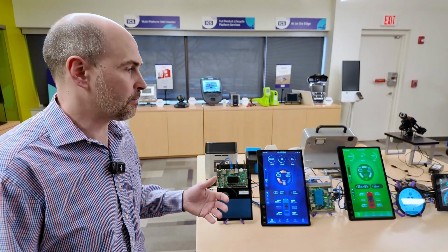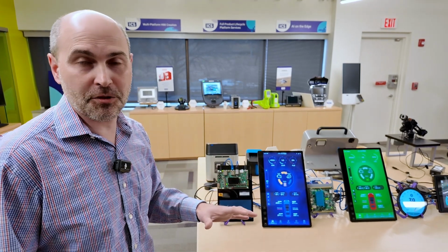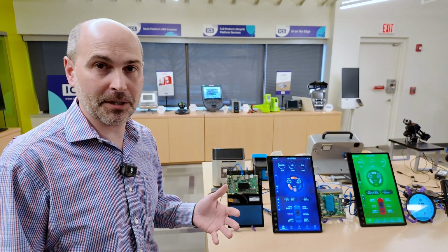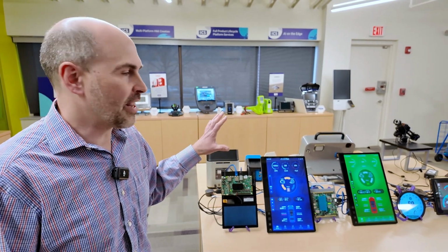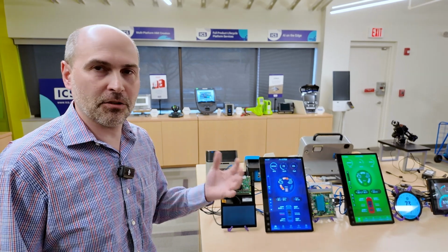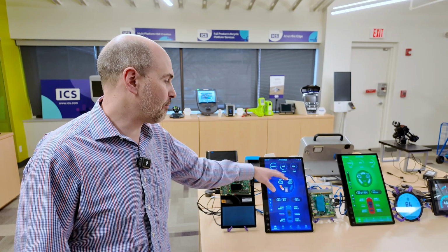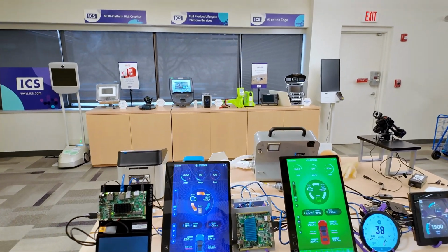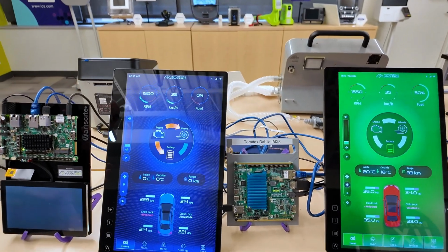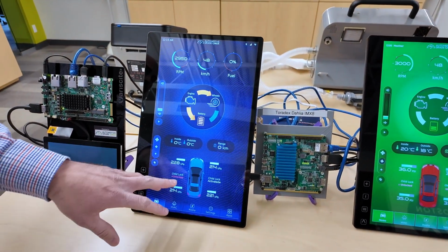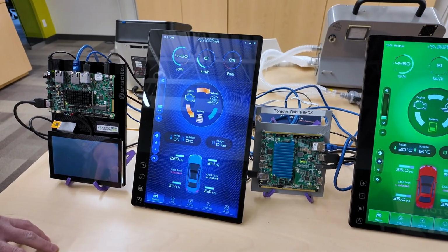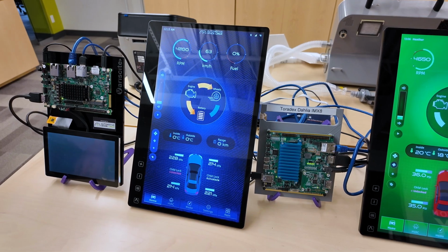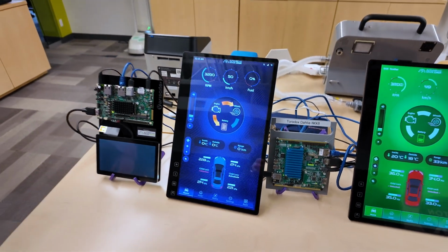a publish-subscribe system. And on top of that, another standards body called COVESA has created the VSS, the Vehicle Signal Specification, that defines basically what the data looks like to a car, such as what RPM, how fast you're going, how much fuel, whether the door locks are actuated. And you can talk to the Kuksa broker over gRPC to query the state of the door locks, find out if the child locks are activated, control the actuators to actually move the locks, all done with this basically abstract API through the broker.